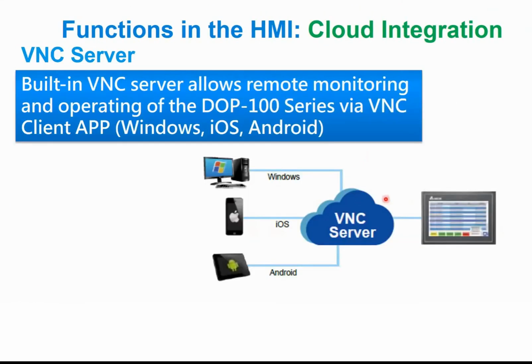One of the limitations of this is that you have to be on the same network. For example, where you are connected from your country, if I have one of these devices here and you have an HMI in your factory, I cannot control your HMI from here. Why? Because I'm not on the same network. My device has to be on your network for me to be able to control your HMI.